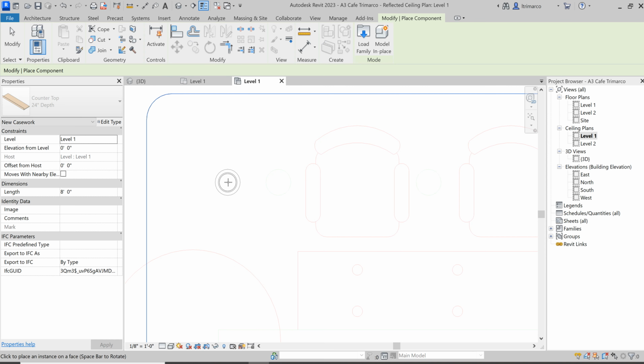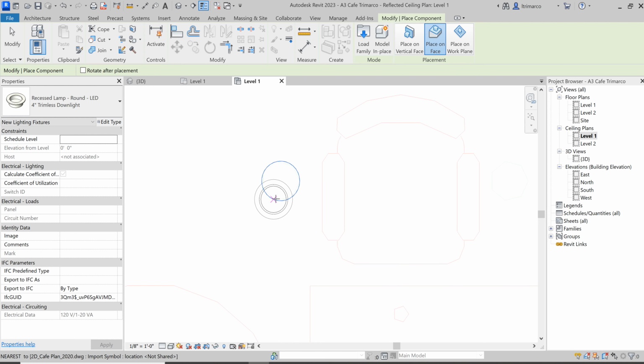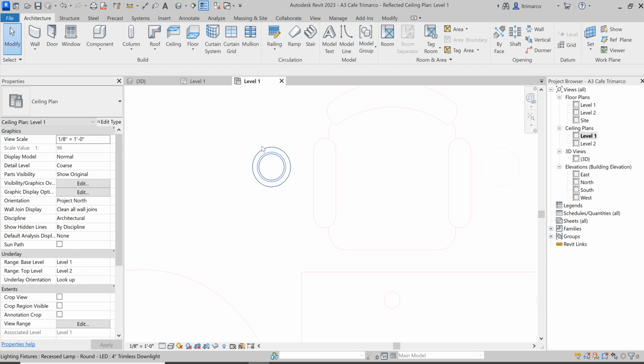And again, within a minute, probably you're going to see, obviously, the Revit family. And you're going to see if I move on top of my CAD drawing, it will turn blue. Again, zoom in as much as you need to see. Again, I can't object snap, unfortunately, to that AutoCAD drawing, but I could just place one as best I can. I could take a look at it in 3D. If it looks good, then I can copy it with constraints in Revit.